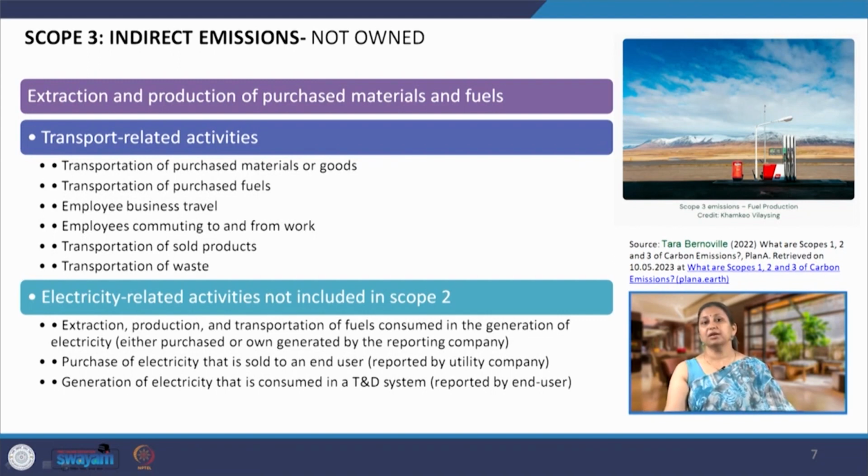For example, if I have to make a wall, I have the option of making the blocks as CSEB, compressed and stabilized earth blocks, which require no firing, no fuel is required, and only a very minimal amount of stabilizer, which might be cement, and the clay, the mud that is procured from the site itself.